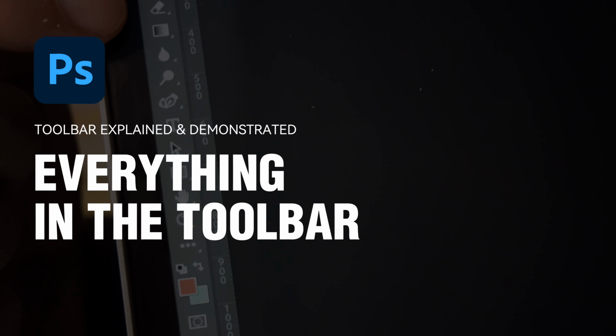2. When you already have a selection, holding the Option or Alt key can help you make a selection that subtracts from the old selection. If you start the first selection by holding the Option or Alt key, you can make this selection from the center of the rectangle or ellipse. And if you hold the Option or Alt key together with the Shift key, you can make a square or circular selection from the center.